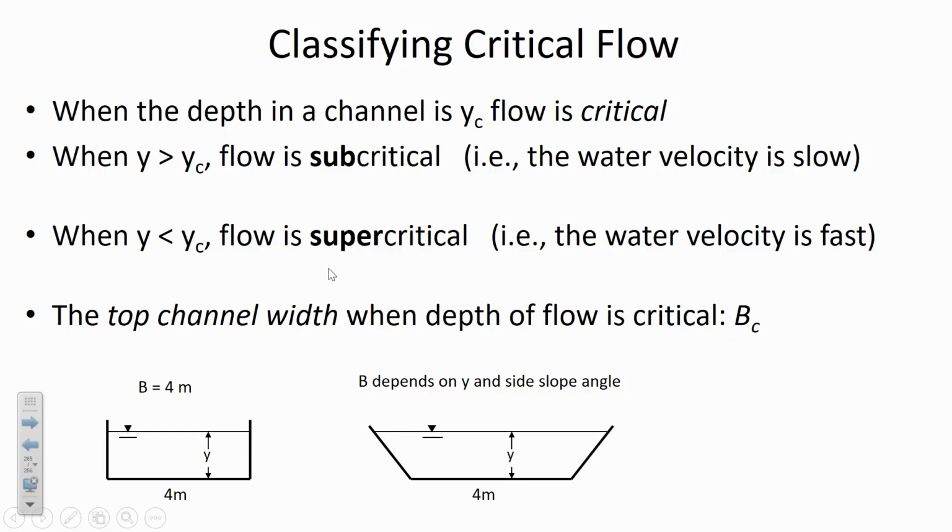So you may remember that in an earlier assignment you classified the flow regime. And your classification was supercritical or subcritical. And that was based on something called the Froude number. Here's another version of the Froude number. They're showing Froude number squared as flow rate squared times the top width divided by gravitational constant times area to the third power.